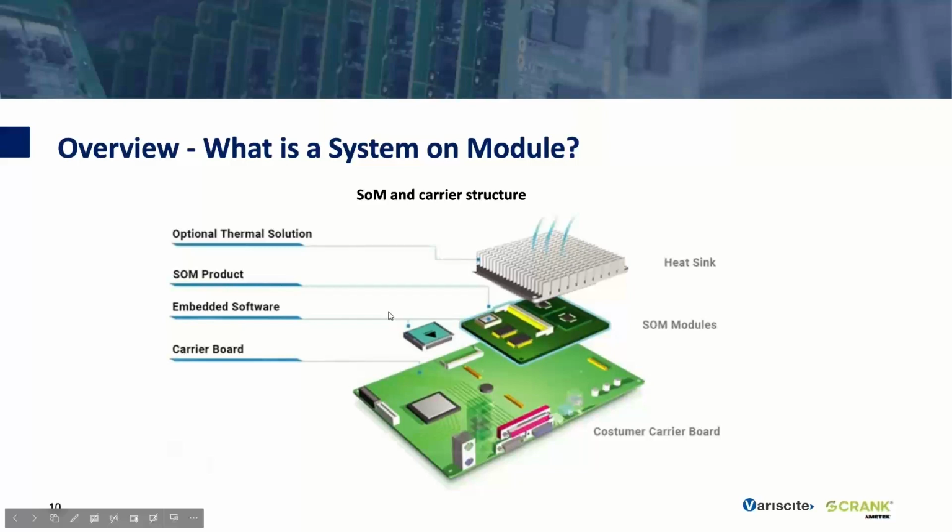You can just reuse it and simply customize whatever is on the carrier board. We provide a reference carrier board, but you can start from our carrier board, remove what you don't need, and add what you need specifically for your project. But let's say that this is something quite easy. You don't have to deal with the low-level process of setup of the hardware. You have a system that is specifically booting just with the SOM. In charge of the customer, there's only the customization of the peripherals outside the SOM.